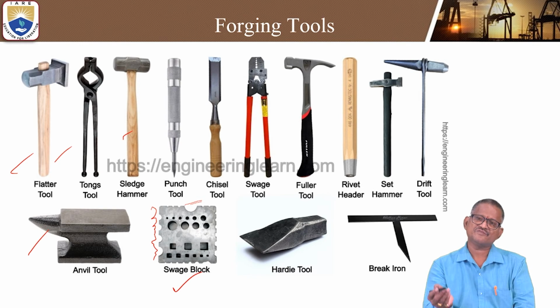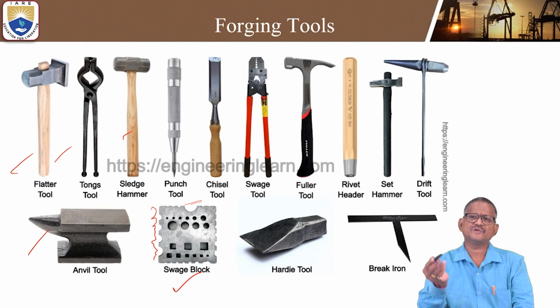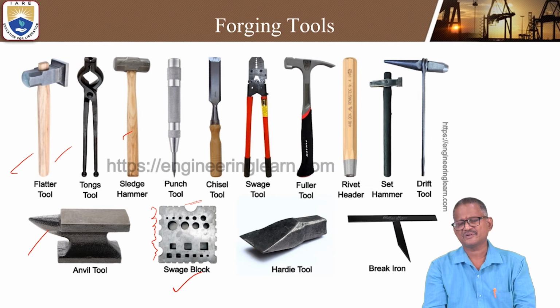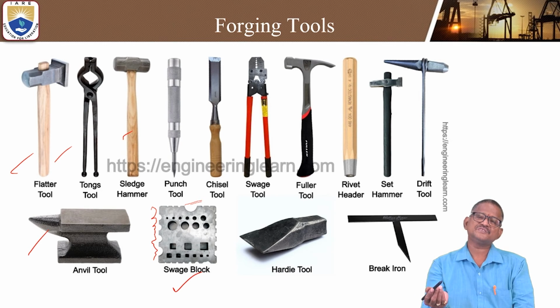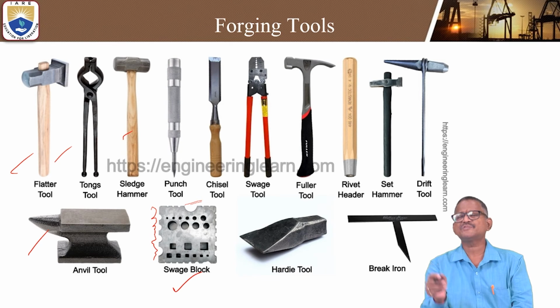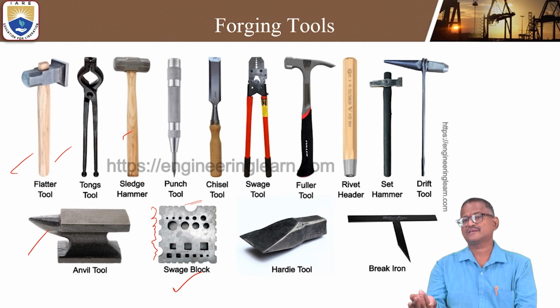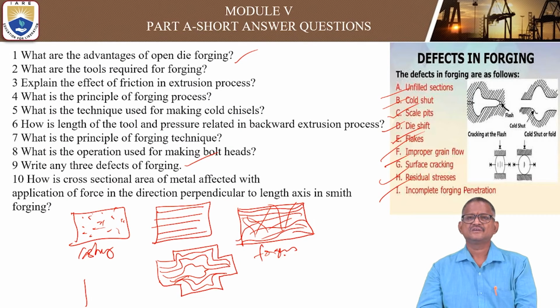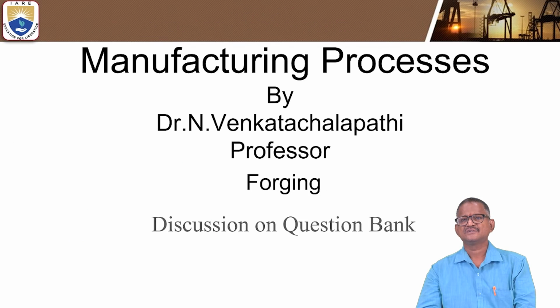When you want to perform drop forging, you need a drop hammer, rivet header, puller, some other type of metal tools, or a press machine, meaning presses are required in order to change the shape. There, very few tools are required. Automatic presses, mechanical presses, and electrical presses are more widely used.